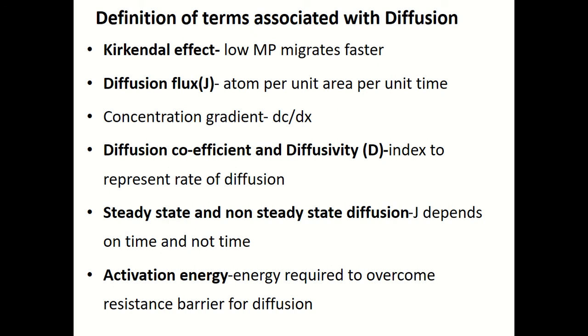It depends upon the diffusing species, which species is diffusing, copper atom or nickel atom, the composition of the medium into which diffusion takes place, and the temperature. These three things the diffusivity or the diffusion coefficient depends upon. Okay, thank you.